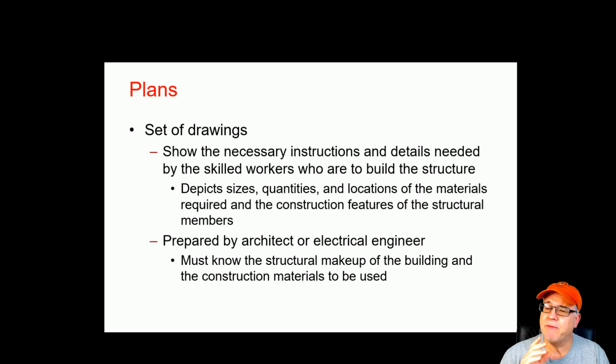Now, if you're doing something where you just have a blank canvas and you're the electrician that's laying it out, it's really important that you understand all of the nuances, because you might need to look at the architectural drawings. You might even have to look at the building drawings, because you need to see what height you put your receptacles on a countertop. So what's it above the finished floor? Or maybe you have luminaires outside on the side of the dwelling, and you need to know what height to do them at. And all these things are going to be covered in the architectural drawings page or the building construction page. So you want to be familiar. It's not just the residential electrical pages that we're worried about.